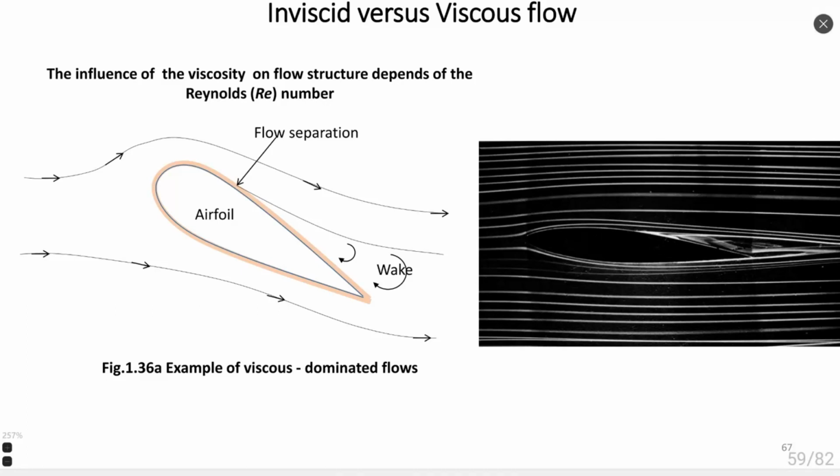Flow separation is not a desirable process, but it naturally appears, right? And we need to understand how to predict and how to manage this kind of flow. We see that there are almost no analytical calculation models. This is why numerical simulations of separated flows and experimental methods of studying aerodynamic bodies become very important.